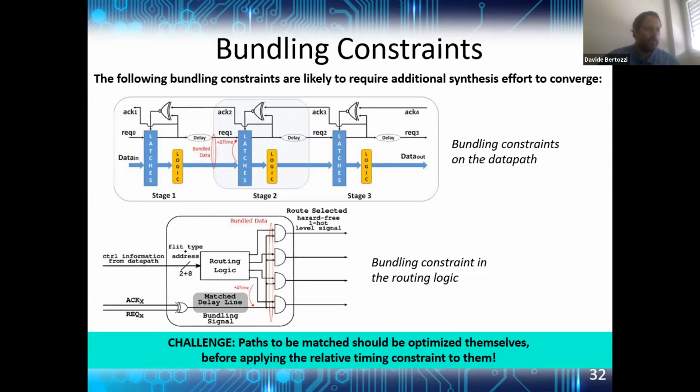So we want to synthesize these data path lines and this routing logic for maximum performance. So we need to tune the bundled control signal to an already locally optimized data path or control path delay.